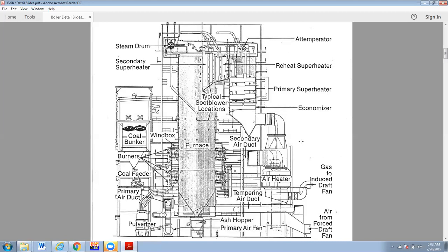An N2 molecule will split apart into two N's, and a single N atom is extremely reactive, and it's wanting to mate up with something and form some kind of a compound. So if it comes up against an oxygen, it's going to make some sort of a NOx molecule that then is going to be pollution if we don't somehow get it out of the gas flow.